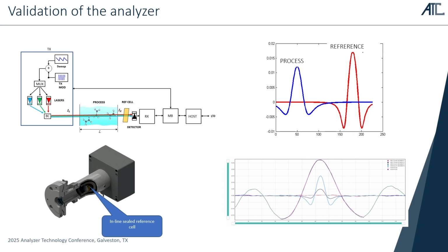In the figure below, you can see the real raw spectra of SO2, H2S, and the blue one is the surrogate gas absorption. They are shown on top of each other because that's the way the analyzer displays the raw spectra, but of course they are at different frequencies, not overlapping. You can also see that the raw spectra quality is quite decent.